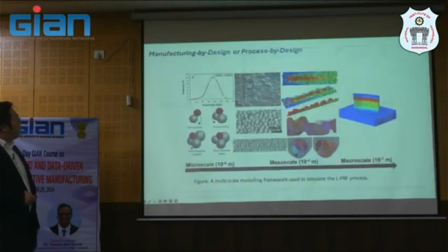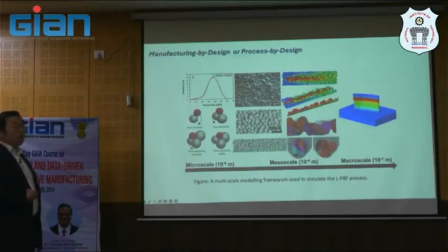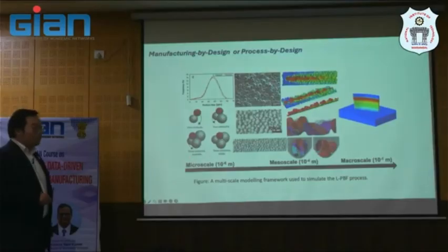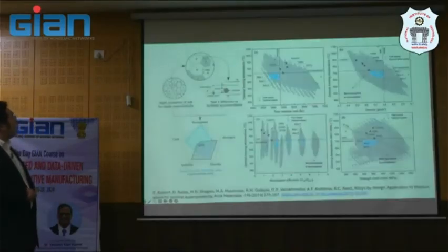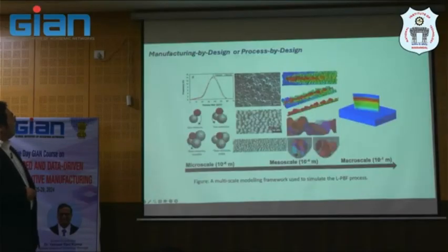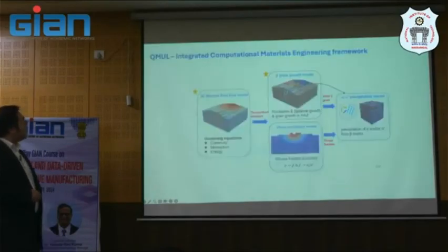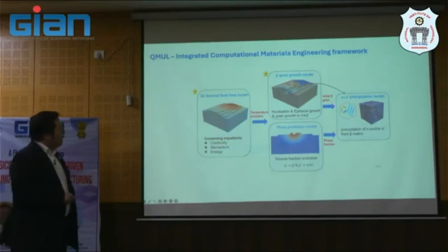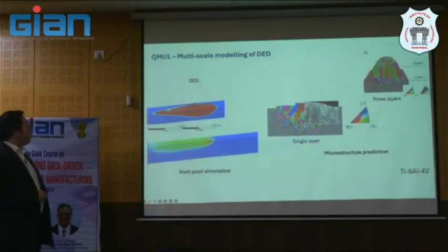And in the backbone of this, we also run some models in the background. That's why it's actually titanium 6-4, looking at this since 2013 on the particle level, molecule level, microstructure, and macro scale. So we will combine the material by design here with the process by design. We'll try to use the framework that I mentioned earlier, where we use the thermal fluid flow for the molten pool, and then a grain growth model to understand the microstructure, and hence another solid transformation as well.